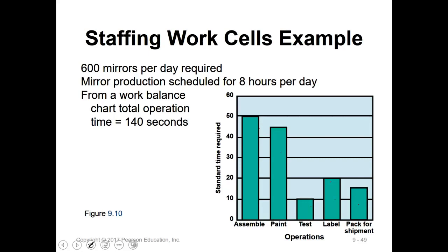So a lot of idle time. This is not a good tasking strategy. You want to make all 3 people pretty much the same working time. And this is what we call balancing.